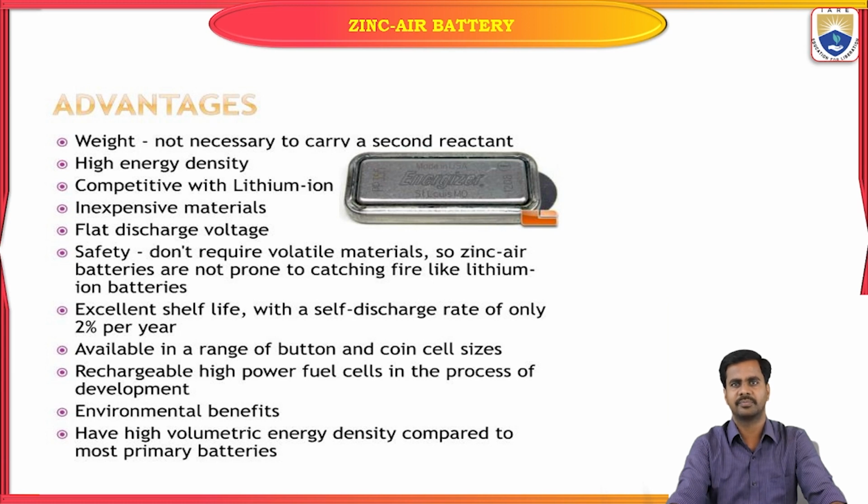Excellent shelf life with a self-discharging rate of only 2% per year. It is available in a range of button and coin cell sizes. Rechargeable high power fuel cells are in the process of development, and there are environmental benefits. Compared to lithium ion battery, zinc air battery is much less hazardous to the environment, and it has high volumetric energy density compared to most primary batteries.